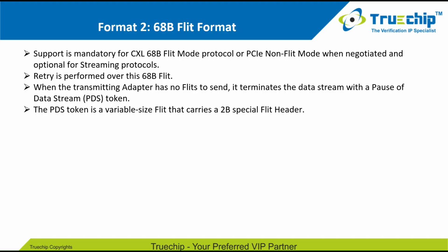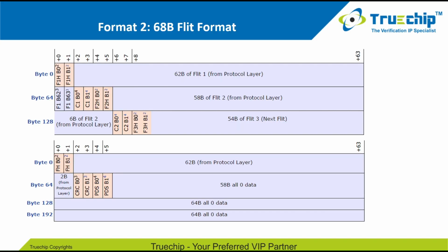As this diagram shows, this format is padded. It also defines a pause of data stream token, which is a valid-size flit used when the transmitter has no data to send.